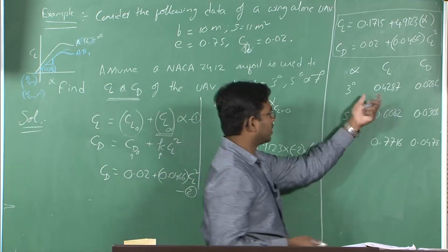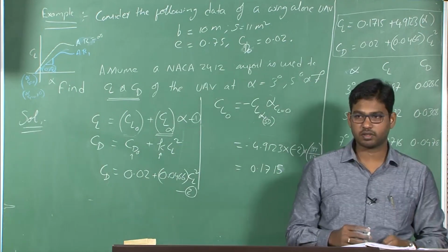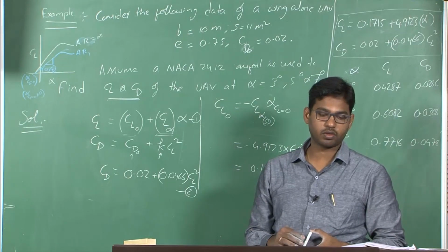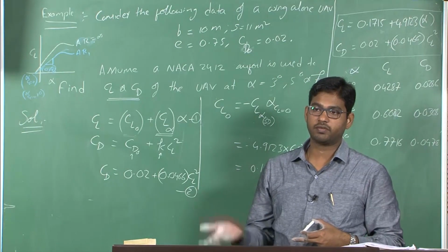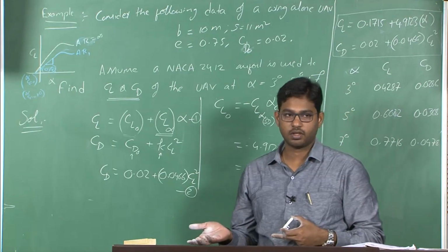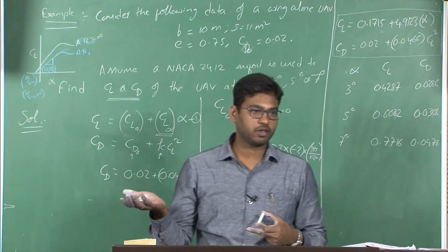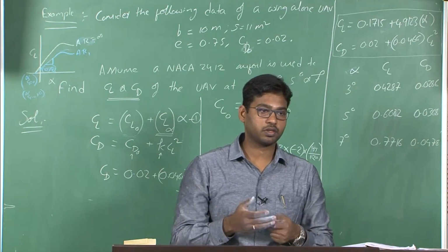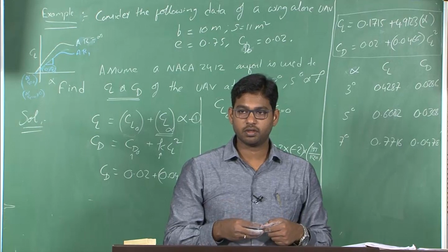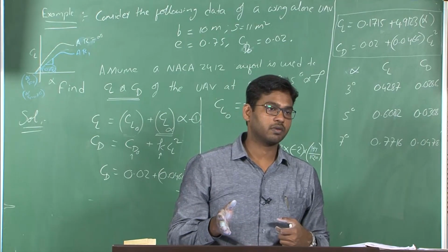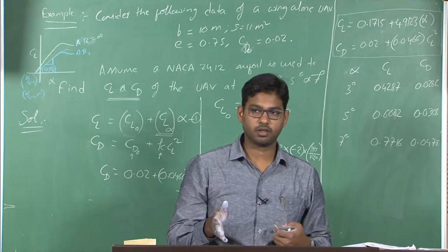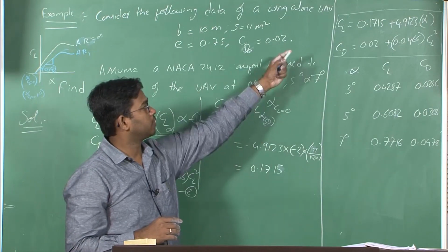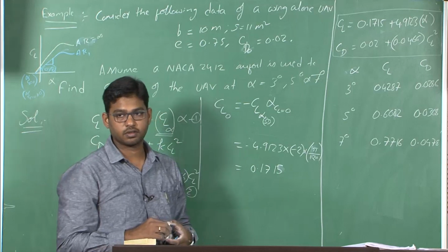Now why do we need to find CL and CD in the first case? You will appreciate it as we progress. Once we start discussing what the lift or design CL should be to sustain a particular weight at a given altitude, that is, how to design the wing and select a planform geometry, you need a design CL. When we discuss those concepts you can appreciate this exercise.